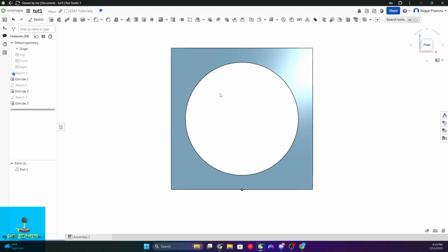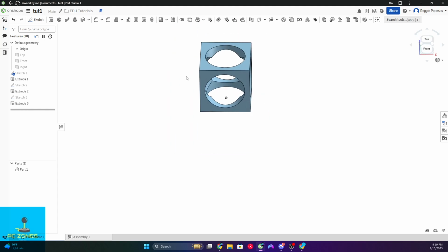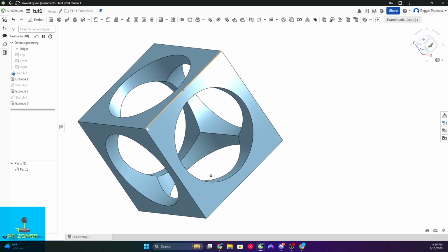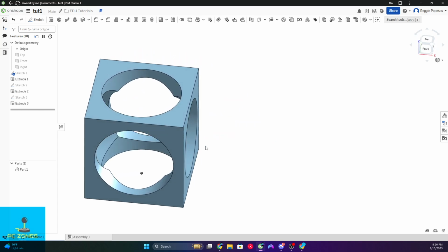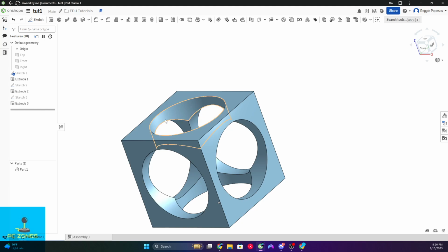We'll learn how to do a nice curvature around these edges. So if you see here, my edges are really sharp. And if you were to produce this type of product, you would have a really sharp corner here, and this is a toy for kids. It's dangerous. So obviously what you would like to do is smoothen out those edges, even if it is by a little bit. So that function is called a fillet.